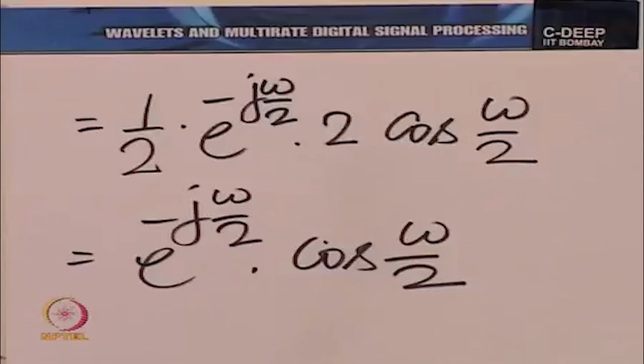Recall that for discrete systems, it is adequate to determine the magnitude and phase response in the region omega going from minus pi to plus pi. We do not need to go outside that range, because the frequency response is periodic with a period of 2 pi. So, whatever occurs between minus pi and pi is going to be repeated around every multiple of 2 pi.